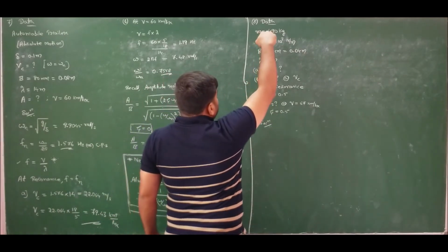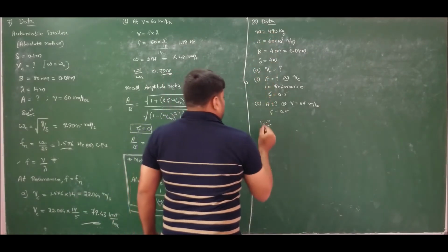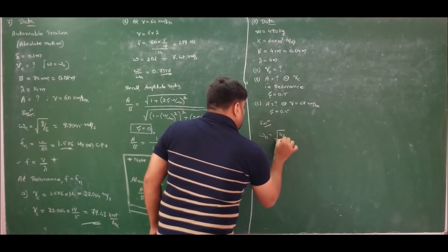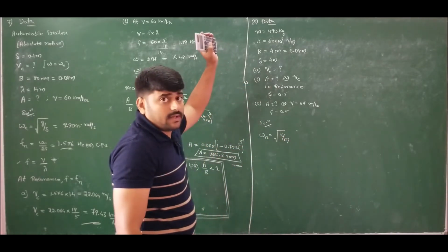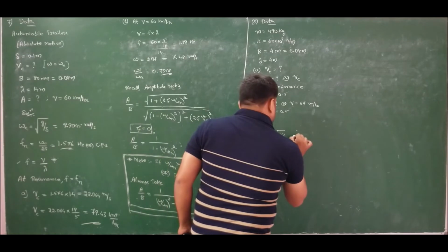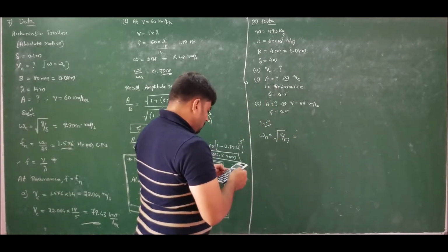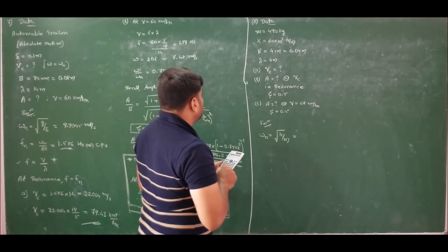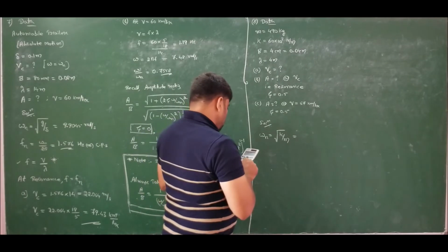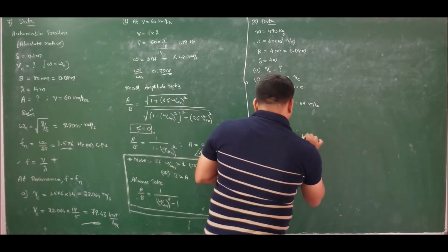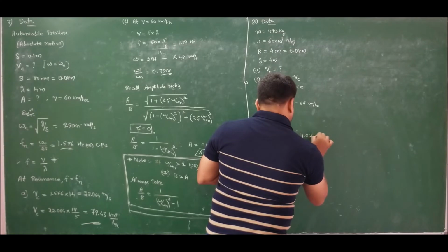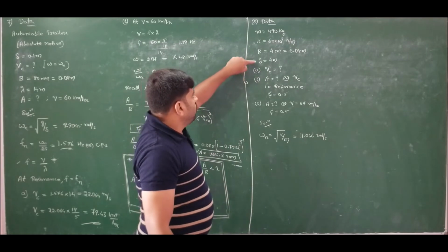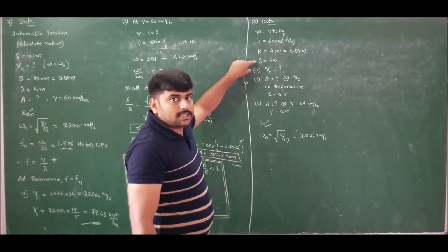So see here is given mass and stiffness. So therefore omega n should be what? Omega n should be root of k by m, because here is not specified the static deflection. So hence if I substitute and solve, how much I will get? It is square root of k is 60 into 10 to the power of 3 divided by mass is 490. Hence the natural frequency is turning out to be 11.066 radians per second.